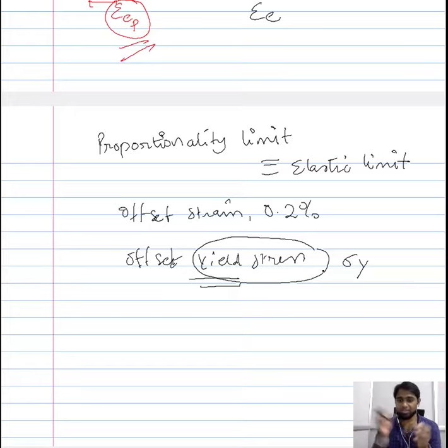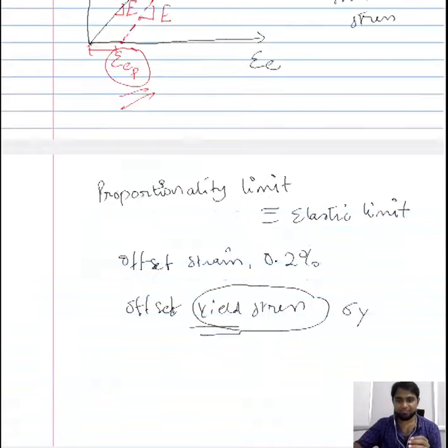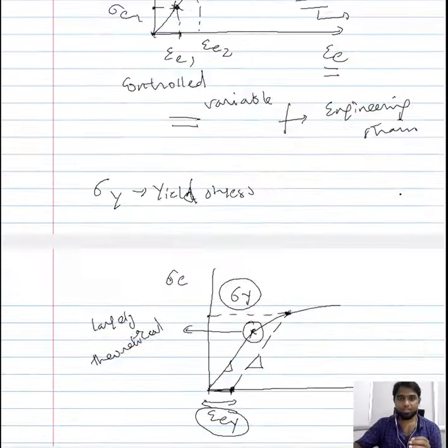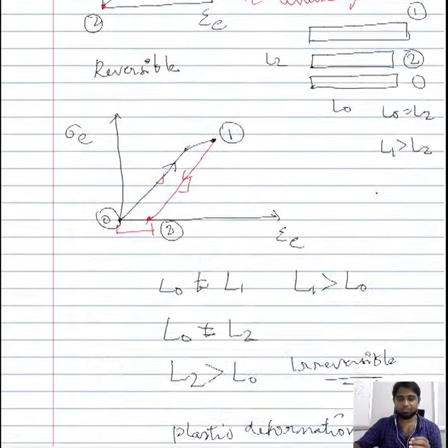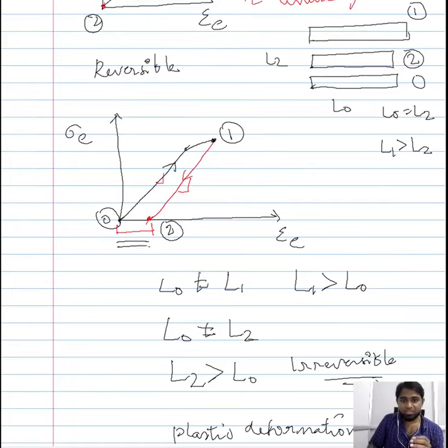And even though there is a resemblance between that path and the elastic region, because of the permanent deformation that has been incurred in the material, there is now a change in the dimension of the material, and that we have seen here in the loading and unloading path. So you have a permanent change in the initial longitudinal dimension of the material.